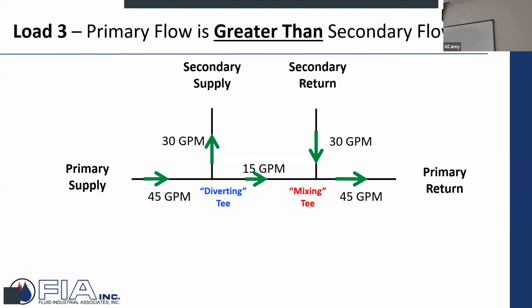This is very, very primitive, where you might get into, and we would get into it over the years, I want boiler return protection. I get cold water coming back from a building. Well, I might take some hot boiler water, put it down the return and blend, mix. And I can do that intentionally. So it's just a quick example, but you have the flows are equal, the primary is greater, the primary is less.